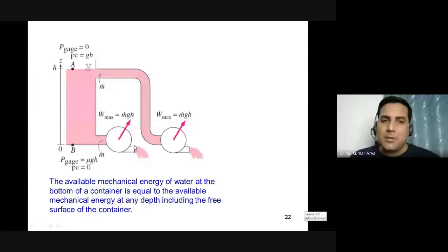So the entire potential energy provided here is being converted into kinetic energy. Your mgh term is balanced by your kinetic energy term, so you can calculate what the velocity coming out should be. The maximum energy available to drive the flow out from here is mgh, because the fluid has come down by this much height. That is the mgh, the energy of the fluid.